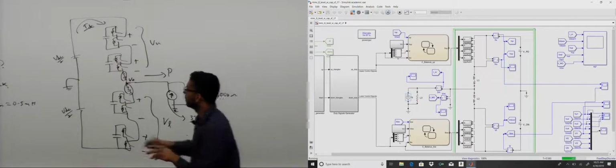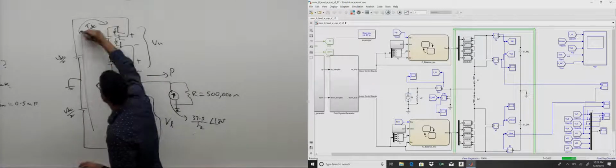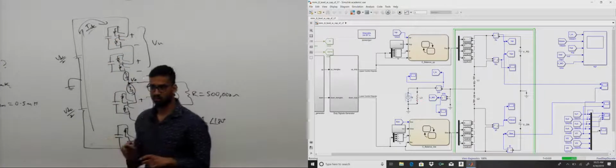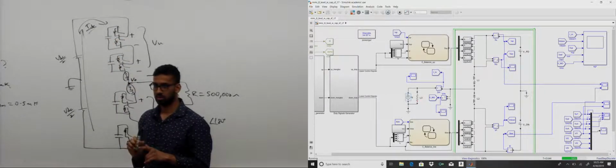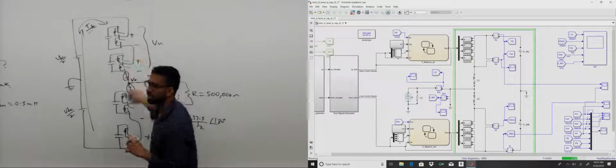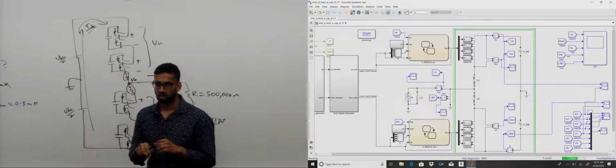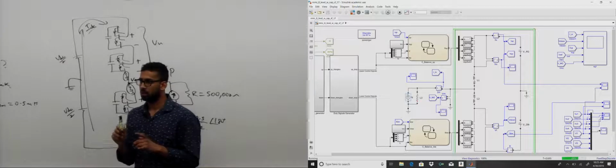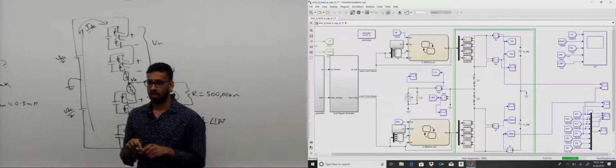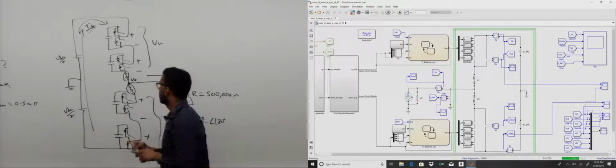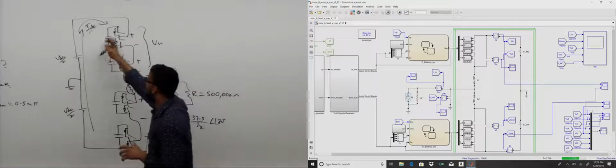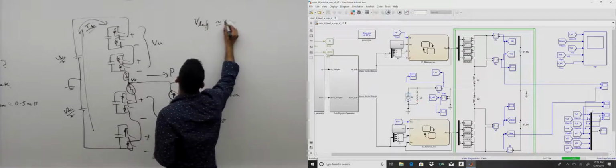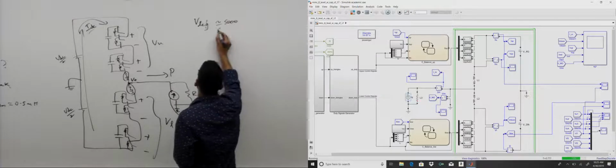VDC. Okay, so you mean this net voltage equals this net voltage? If that is the case, then there won't be any IDC, right? There should be some IDC flowing into this leg for power balance. So, do you think the net leg voltage will be somewhat less than 5,000? It will be somewhat less than 5,000, so that is fine. So we know that V leg is approximately 5,000, and in fact it is less than 5,000.